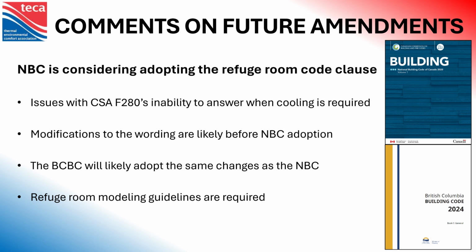So my feeling is they're going to probably make some modifications to that wording before the National Building Code adopts this, because I think they now recognize what CSA F280 actually tells you, and it is not the right tool in its current form to give you that yes or no answer on a cooling requirement.